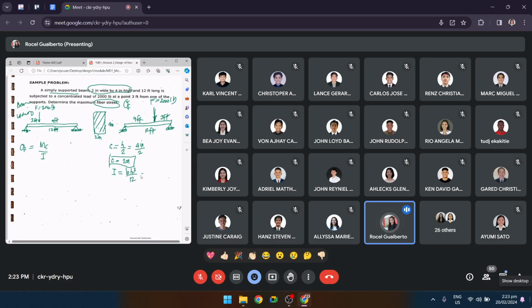Okay? What is our B? B is 2 inches. The H is 4 inches. So B H cubed over 12. So what would be the value of I?